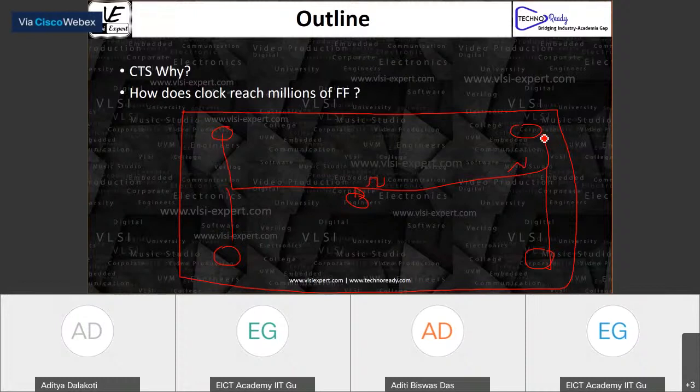Very bad. But if I put a tiny buffer here, and if my flip-flop is small here, then it will still look nice and clean, because this buffer will only see the flip-flop load. So my signal going into the block is still good, but what is coming to it is all over the place. This is where the noise injection, jitter, and everything is getting added. You can still maintain a good slew rate going into your design, but you also have to make sure that the slew rate before that is not bad, because that is where all your noise injections will come in.